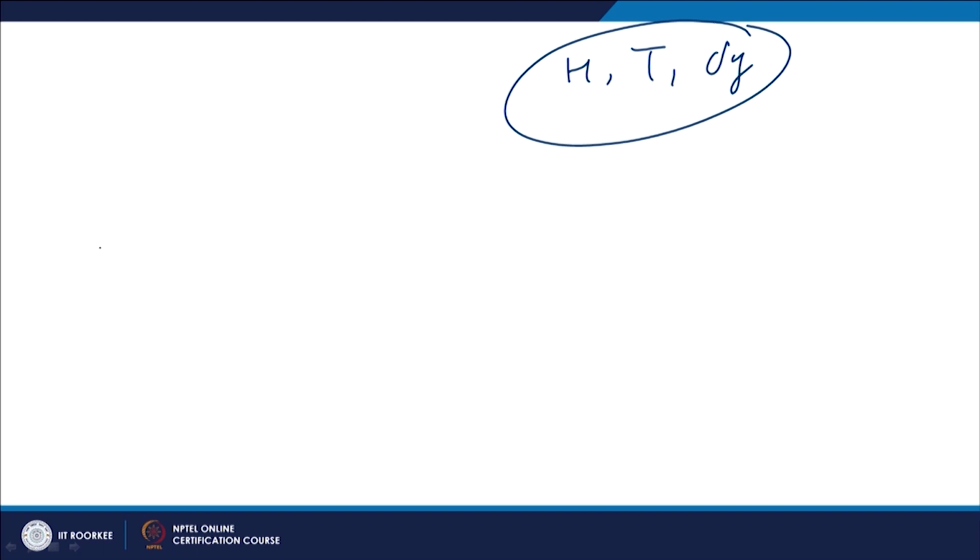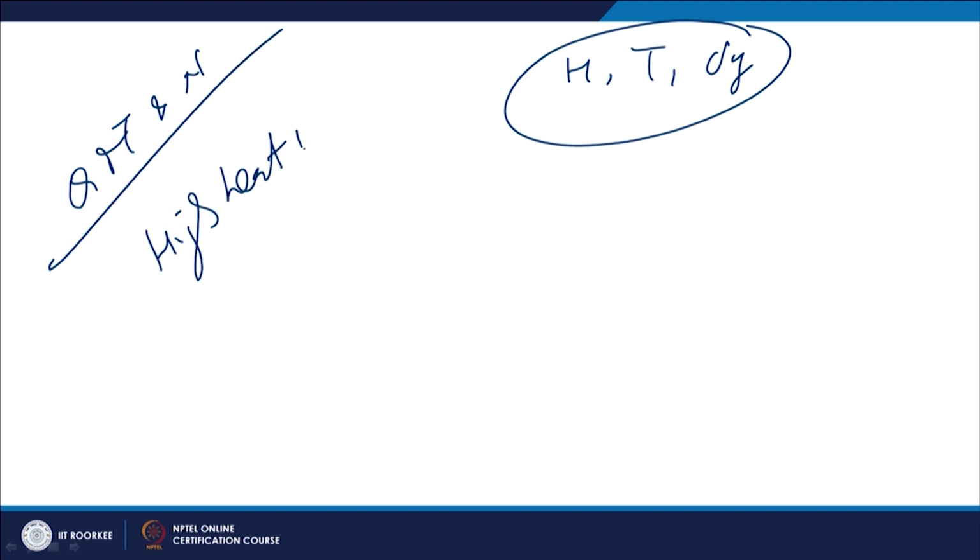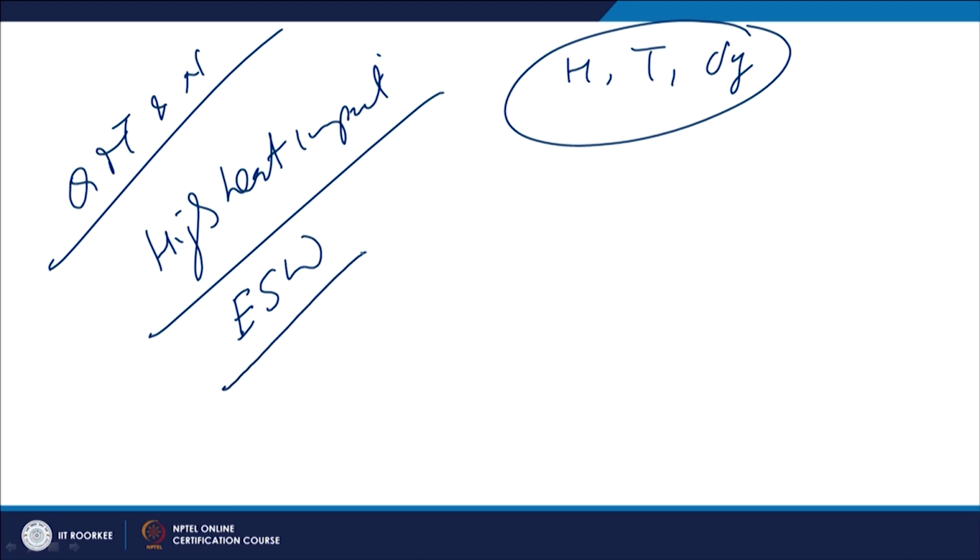In some cases, the steel in Q&T or normalized condition is welded using a high heat input welding process like electroslag welding, or extremely high welding conditions, where the combination of welding current, voltage and welding speed is such that the net heat input is really very high, as in the case of SAW.